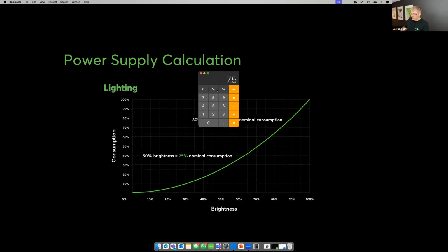So again, if we do this calculation, divided by 24 volts, and we now take our 30%, we've now got 2.8 amps as our calculation. So now we can be looking at a 4.2 amp power supply, which is about a third of the price, which makes sense considering it's 30% of the power consumption. This is a significant saving there. And as your installation grows, that's where you're going to see quite a big saving. So power supply calculators is very important.